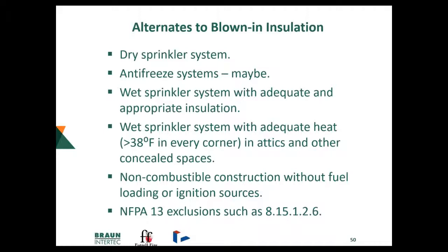Non-combustible construction without fuel or loading or ignition sources. So if we can build a building out of metal and non-combustible materials and keep any fuels out of there, storage or anything else, then we've got an alternative. And NFPA has many exclusions, and I've highlighted one here. You can go to the NFPA codes online and find this one specifically, but 815.126 is one of the exclusions that would apply. But I want to go back to the antifreeze systems just for a moment.